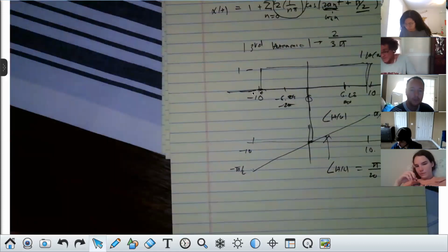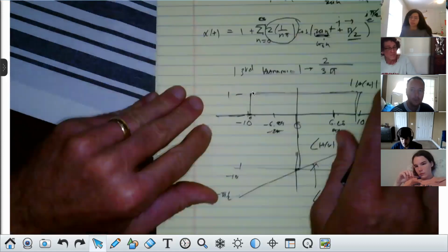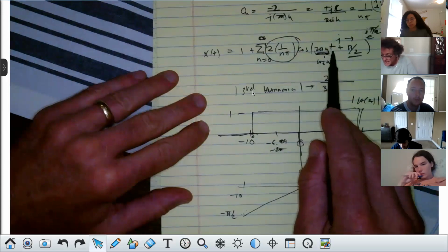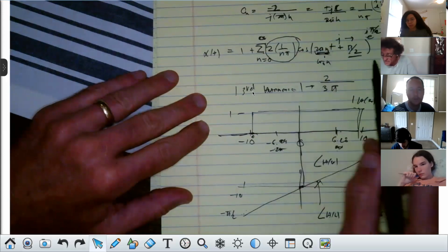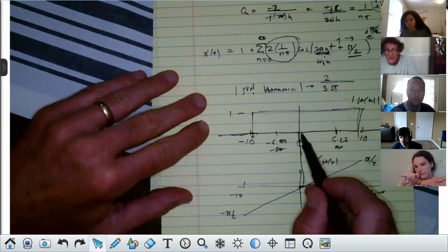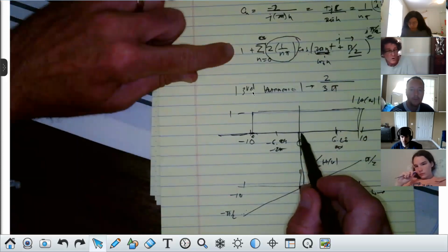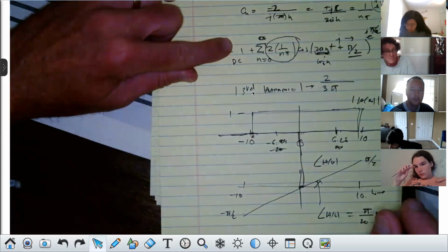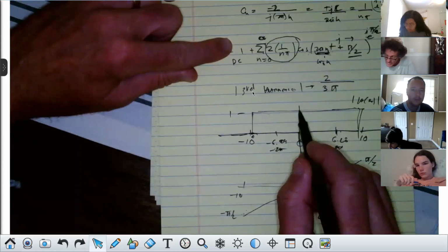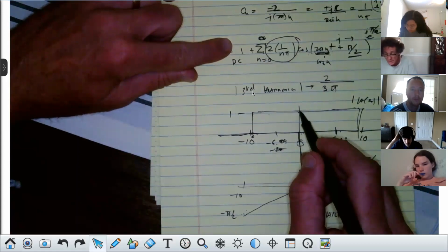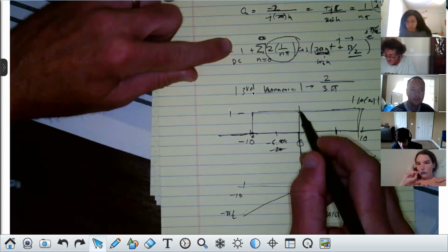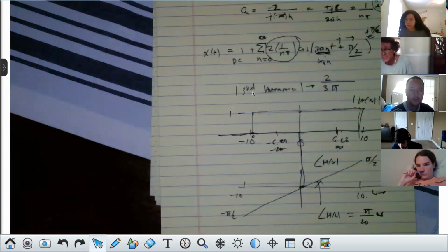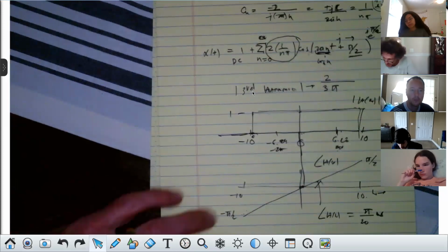Now remember what this type of system is. When we have it in this cosine series, what we look for is the magnitude and phase of the filter at these frequencies, right? How many frequencies do we have to worry about? We have to worry about DC, right? For sure, the C0 is the DC term. Do you agree with me? You can even put down DC here. Now, 1 times 1, the filter has a magnitude of 1 here. So the output is just going to have what? Y of t will just be, it's normally C0 times H of 0, the filter evaluated at 0, correct? But that's just going to be 1, isn't it?